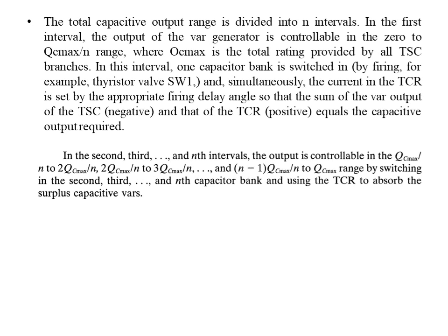So in case of FC-TCR, we were switching the TCR and the FC was absorbing the additional VAR compensation. In case of TSC-TCR, TSC generates the VAR compensation and TCR absorbs the surplus capacitive VARs.